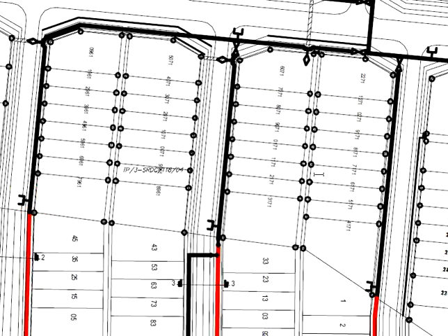As long as you can ensure the water mains can reach the last building here, theoretically you can end your water reticulation system here instead of ending here. Same goes to this side and also this side. You can actually choose to end here and also to end here in order to minimize the construction costs.